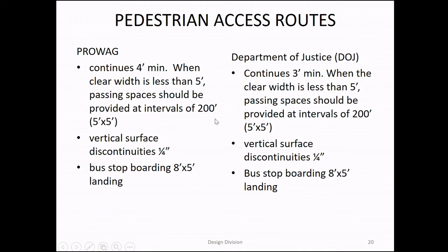If you see that anything is uplifted when you're doing your walk on the sidewalk, and it's more than 1/4 of an inch, that has to be reconstructed. On Mark's project, we talked to road maintenance, and they were willing to grind some of that because it's not much.